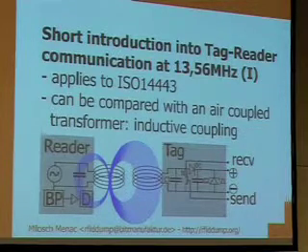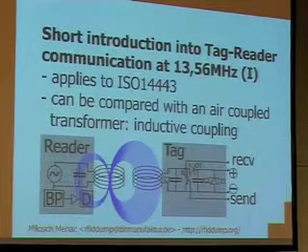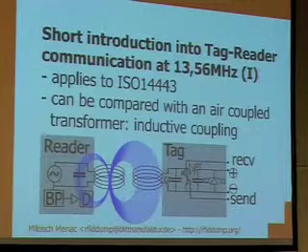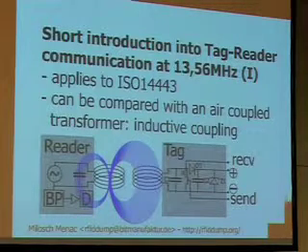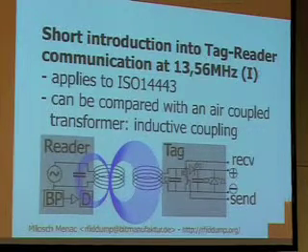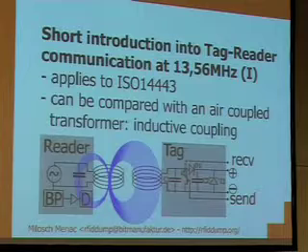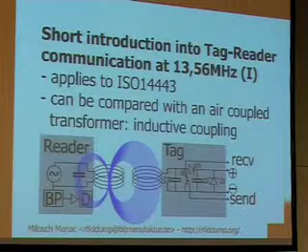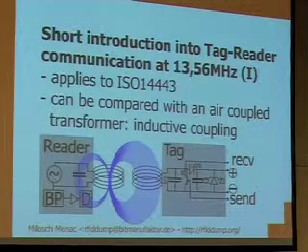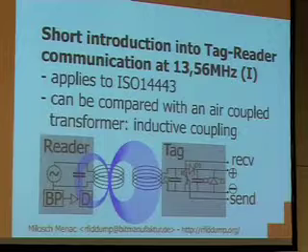And the carrier is received by the tag by using a transformer approach. It's similar to transformers. You have two coils, and it's very much the same as transformers. You don't have the coil that connects it, but you have an open magnetic field. So the tag receives the field. You see C1 that is connected on the tag, and it makes sure that we are resonating to the field, so you can make sure that you have the highest possible output.